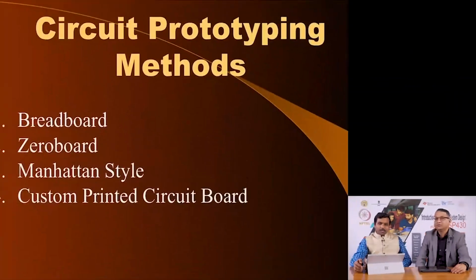So there are 4 types of circuit prototyping methods. First one is breadboard, second one is zero board, third one is Manhattan style, and fourth one is custom printed circuit boards. Now you see these 4 methods have their own advantages and disadvantages. The breadboard style method is often called the quick and dirty method, because it allows you to quickly put together a circuit that you have in mind and test it. Of course, the issue is that the breadboard is not very conducive for testing high speed or high frequency circuits.